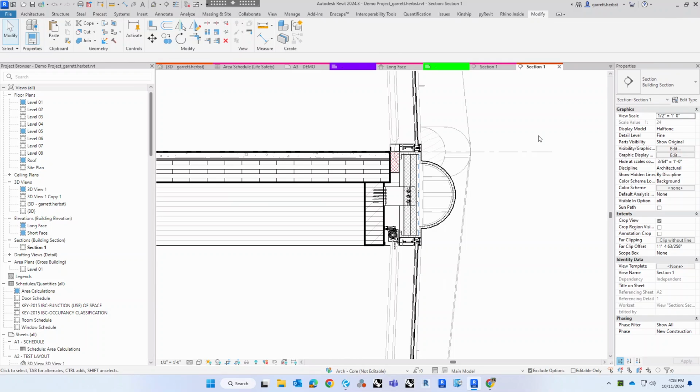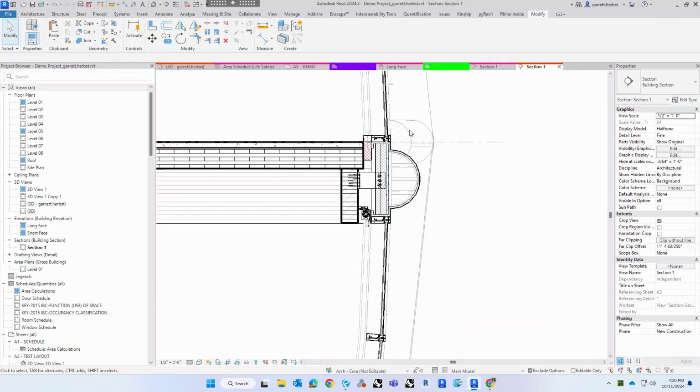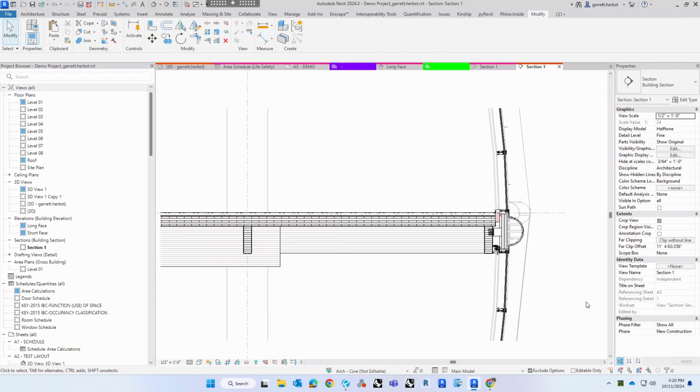And again, we don't add all the detail into it, but we would likely take that structural component and move it down. We would offset the curtain wall system so that it's in line with where the detail needs it to be. And that all plays a factor when structure is laying out their slab edges, their exterior beams, columns, all that good stuff. And also when we're factoring in occupancy calculations and when the GC is creating shop drawings based off of our elevations and whatnot.